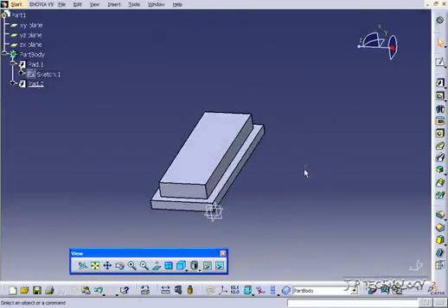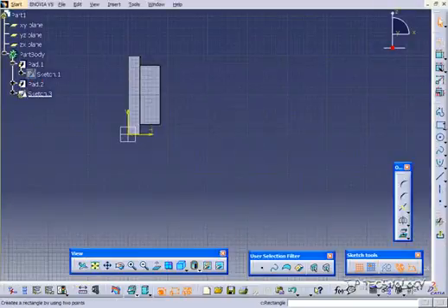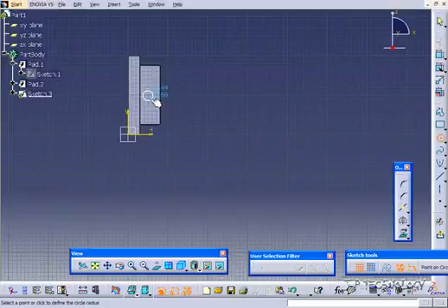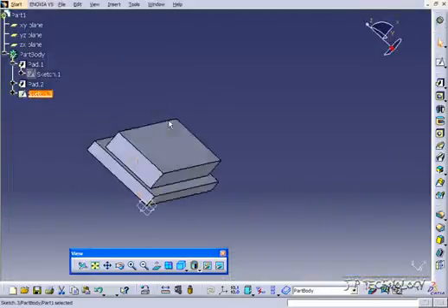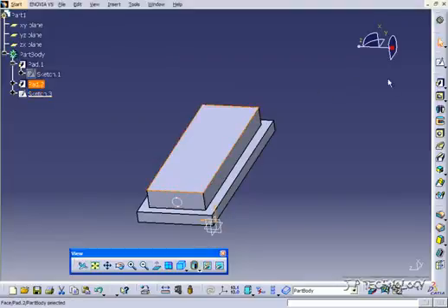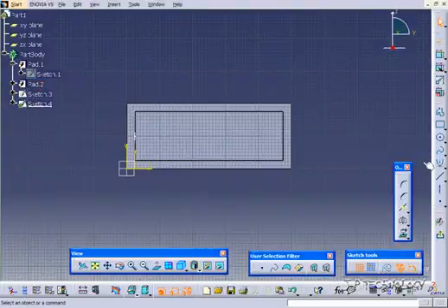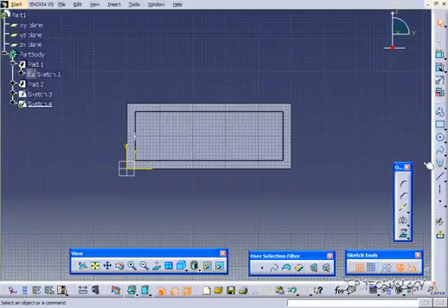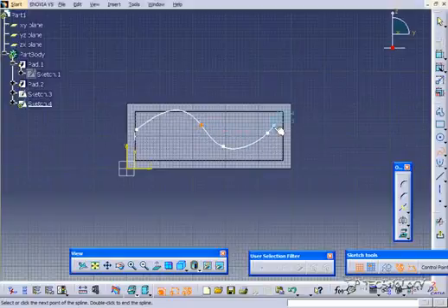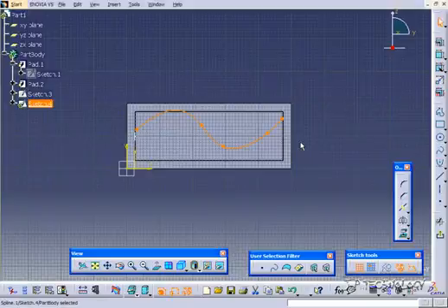and this time let's create one that isn't a square. So let's do a circle like we did on the last one. So let's click this face, click sketch, and we'll click circle. Just draw a little circle in there, and we'll go back, click the top face here, click sketch, and as we're going to be able to cut through this, we can make a route for it to follow. So if we use the spline tool, you can make a little path and a little route, and everything's going to follow and cut right through it. So when you're doing this, this can be like tubing or piping that you want something to follow through.